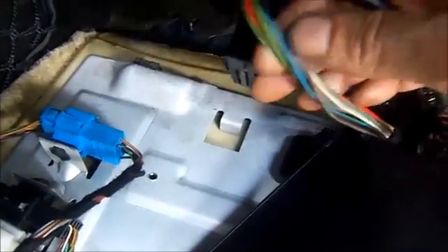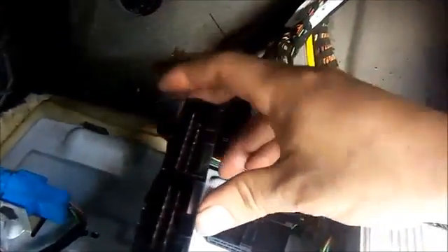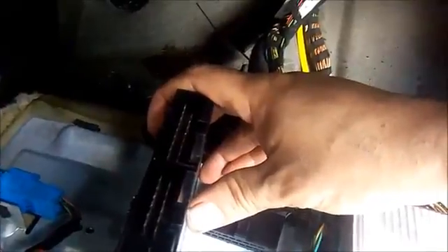This is very normal when that seal leaks. It travels through all the wiring, and I've seen the Mercedes vehicles that this transmission goes underneath the TCM control module, goes underneath the hood in the TCM box or in the computer boxes, and sometimes I see the TCM all the way up with transmission fluid.